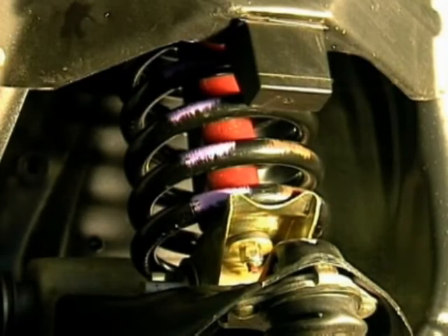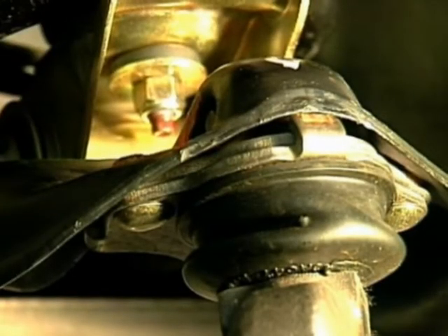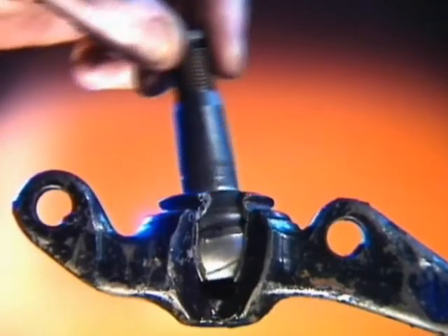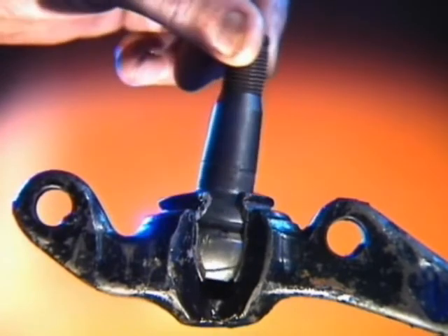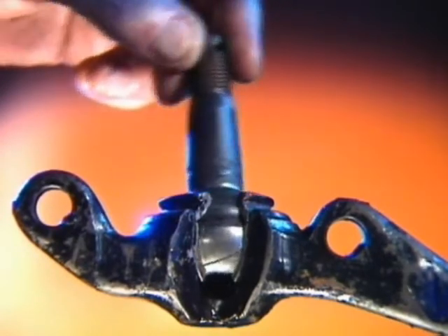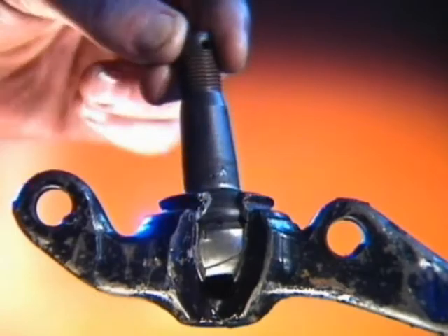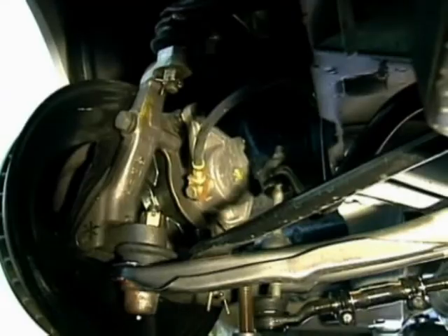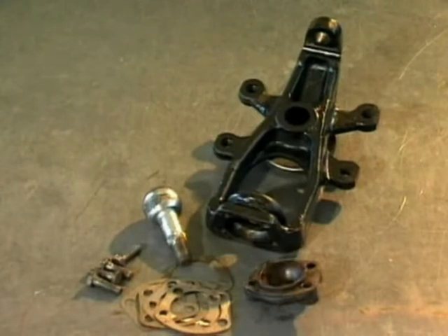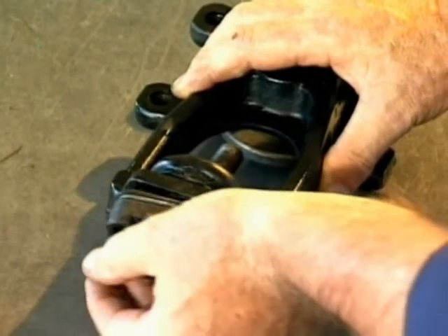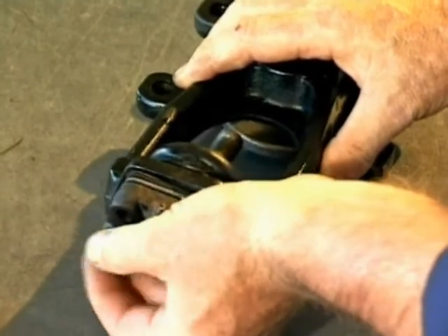The ball joint can be a sealed, self-contained unit fastened to the control arm in a number of ways. It is made up of a pressed steel housing fitted with sintered iron seats and a hardened ball stud. A taper on the stud locates in a mating taper on the suspension unit, and a rubber seal keeps out dirt and water. Some ball joints can be dismantled to replace the seats and ball stud and allow for adjustments.